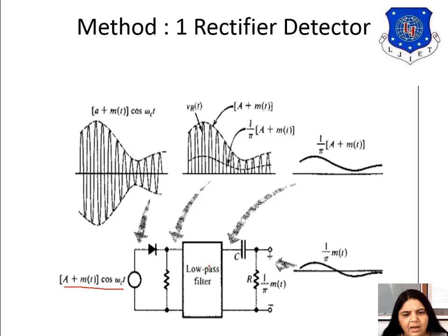Now at the low pass filter output we have the component that is AC plus DC. Again, we want to remove that component also. This DC value we can eliminate by passing it through the coupling capacitor. Now we can have the output across this resistor, having a 0 DC value.